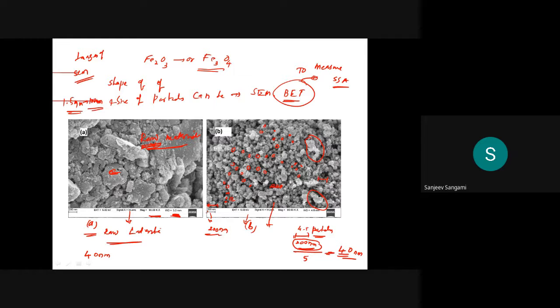If you convert that, you will get even smaller sizes also. But if you want to find out the fineness of the cement accurately, and the shape and size of the particles, we should go for this kind of images, that is scanning electron microscopes. Otherwise you won't get any images directly, you'll get the value in terms of square meter per kg of the cement.